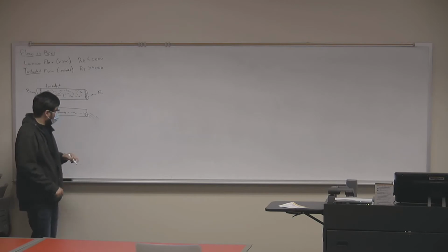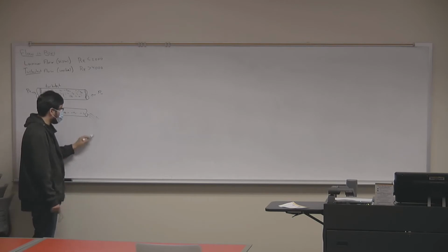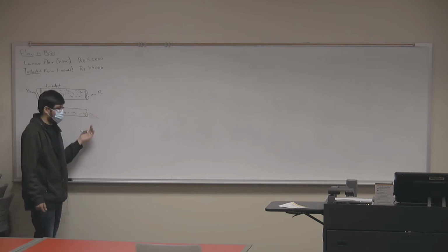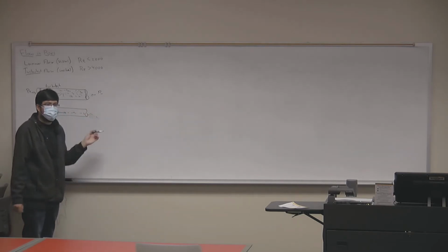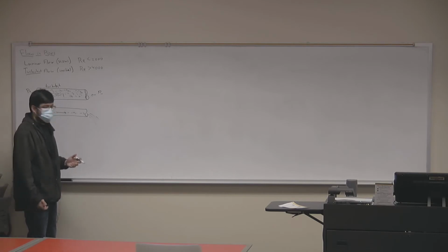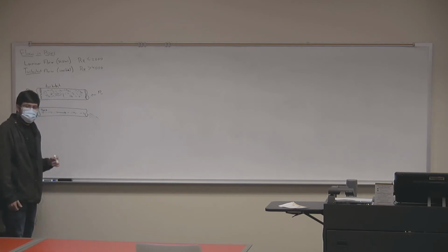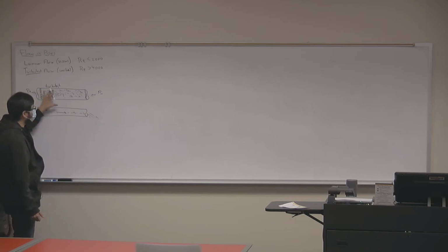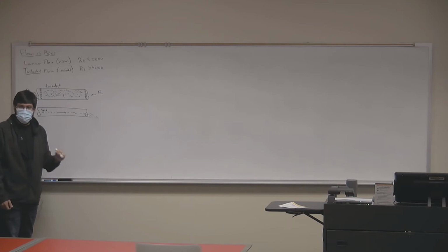Well, one easy thing to do is to figure out how much volume the pipe is transporting, how much volume, and how much time it takes. You get volume over time, you get flow rate. You divide it by the area, you get average velocity. So doing something very simple, not really mathematical, you can find this average velocity. And that allows me to not have to worry about this erratic movement by dealing with average values.